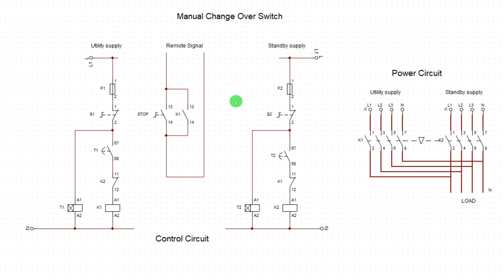So that is what you're going to use. You're going to buy male and female or that socket. So the male and female, you connect it from the genset and also socket it that way. So that whenever you want to carry out your maintenance of the genset, you unplug that connector, that particular male and female plug. When you detach it, you now isolate this function. So the mechanic or the maintenance of that genset can now service it and start it and test it. Then when you are done, you plug in that cable again.